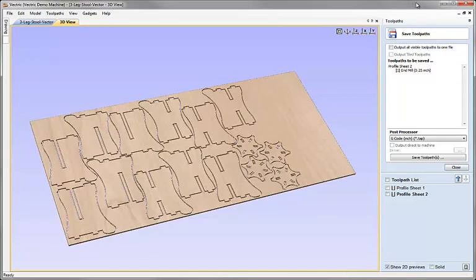So before we conclude this tutorial, I'd like to show you another option that we have with the profile toolpaths. Let's imagine in our scenario that after we cut our parts, we realise that it would be beneficial to us if we could change the order that they would cut. Perhaps we have a vacuum system that would benefit from us cutting the parts furthest away from this side of the machine and then working back towards this side and keeping the strongest pull of the vacuum as we cut out the parts and release some of the vacuum pressure. Let's show you how we could achieve that.